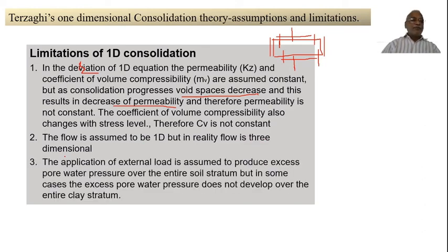The third one, the application of external load is assumed to produce excess pore water pressure over the entire soil stratum, but in some cases the excess pore water pressure does not develop over the entire clay stratum. So when you put the load, the water that is present inside these pores will be developing some pressure.